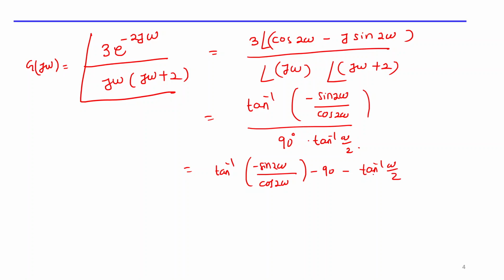Now after you find this value, what you need to find is the phase margin of the system. In this phase you put omega gc in place of omega, which is 1.266, and find the angle phi, whatever angle you get.